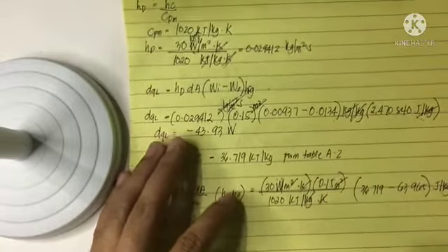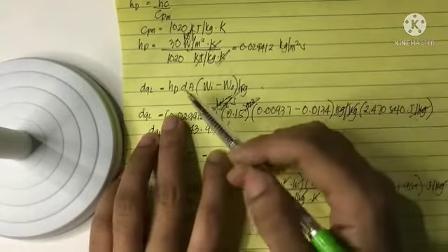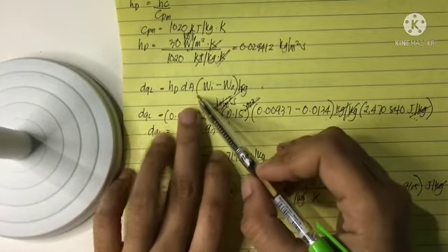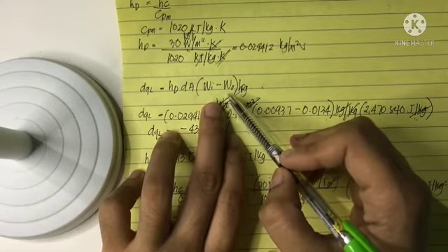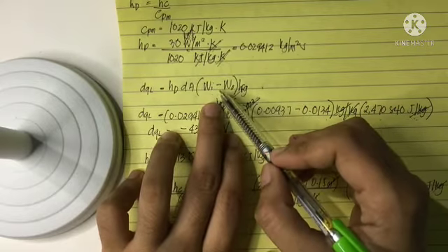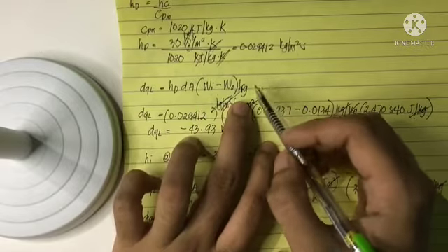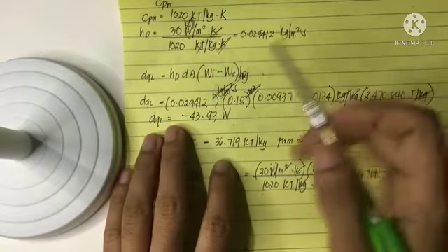So solving for the rate of our latent heat, it is equal to the proportionality constant times our area times the humidity ratio difference of the air and the wetted surface times the latent heat enthalpy.